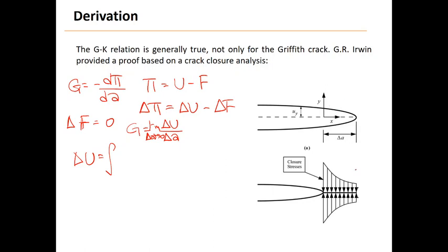Now, that is actually equal to the amount of displacement that the crack has opened, right? So originally there is a crack here, so the two pieces of material are intact, but this point has moved up to here, and likewise along this whole line of delta A, they correspondingly moved up because the crack has gone through.